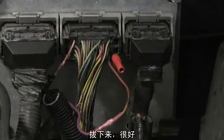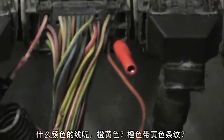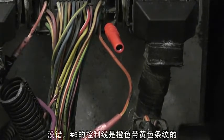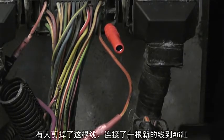Just pull it. Good. So you can see that somebody has cut this. What's the color of that wire? Orange with a yellow tracer? Yes. Our number 6 control wire is orange with a yellow tracer. Somebody has cut the wire and rerouted a new wire to cylinder number 6.